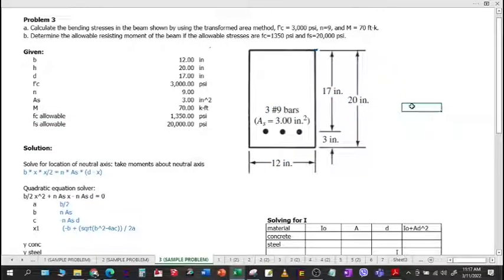Now, if I may illustrate, the beam profile would look something like this sideways. I'm trying to exaggerate the bending here. So if a certain beam is loaded as shown, it will have this bending, and if this is your neutral axis, everything below the neutral axis will be tension, and everything above will be compression.